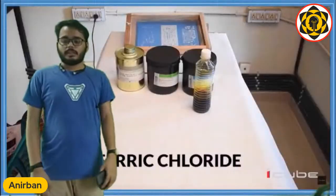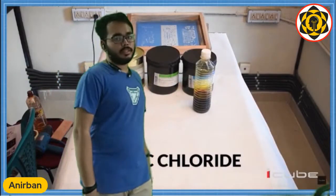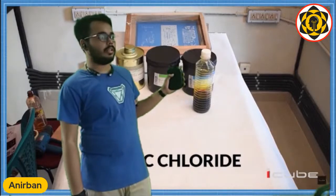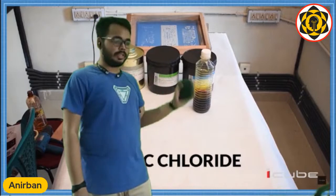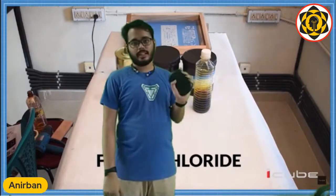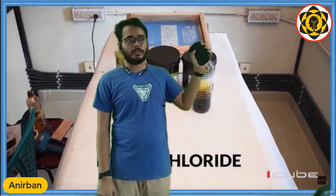Then the most toxic stuff, ferric chloride. This thing is a very concentrated acid. Okay, and if you dilute it, it won't work on the PCB. So you need it to be concentrated, but it is very dangerous when it is concentrated. And as I said, it's acid, so it will eat anything except maybe plastics, polycarbonates and fiberglass.